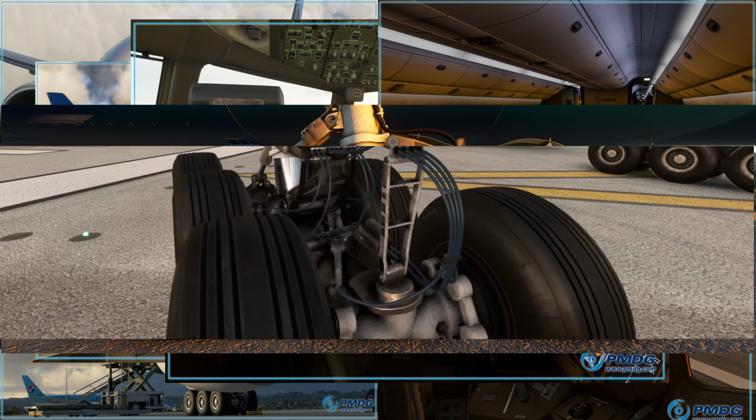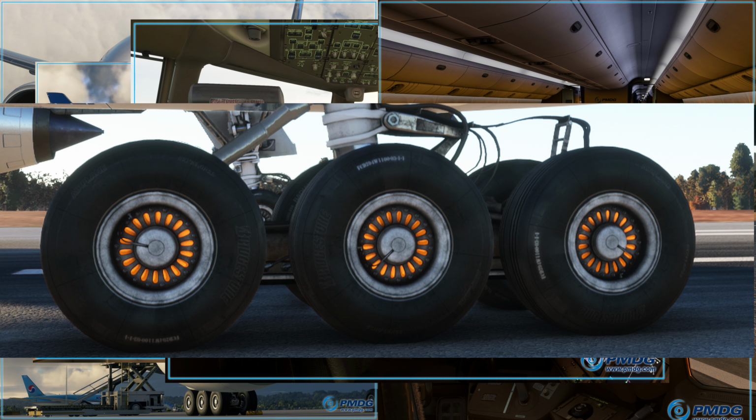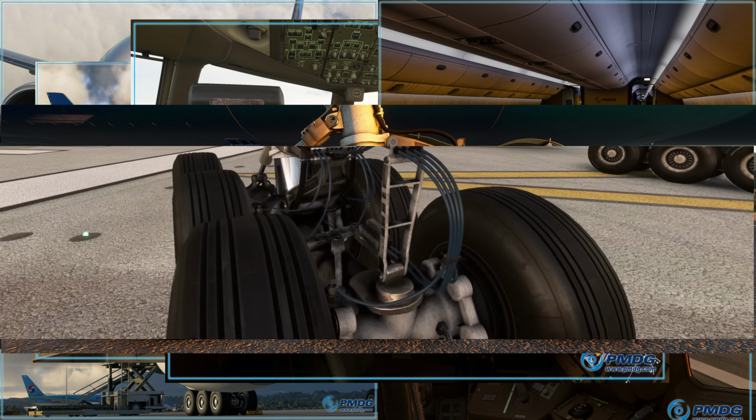Finally, we have to keep in mind that the airplane carries a huge amount of energy, and obviously that energy can really heat up the brakes. Now, I'm going to spoil you a little bit with a picture that's going to come later. When the brakes really heat up, they can start to glow. But for now, when we retract the landing gear while the brakes are really, really hot, imagine, for example, you do reject the takeoff at a higher speed, you ignore the brake cooling time, and then you take off, retract the gears with the hot brakes going right into the gear bay. That can most certainly cause a wheel well fire warning.